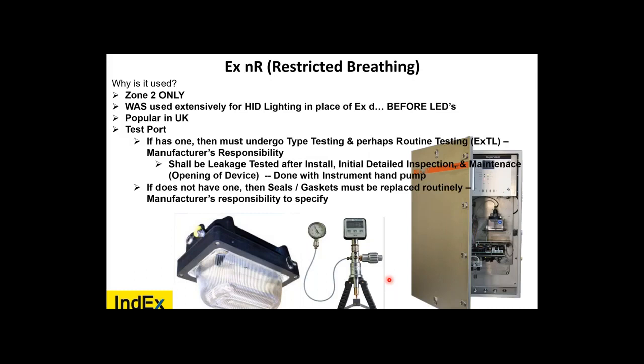Here's the problem with ATEX: manufacturer self-declaration. Now, if you involve an ATEX notified body like Ex NB or other ones, well, they know how to do the testing, or I should say, know which testing has to be done and who it can be sent to. Now, does it have to have a test port? Well, if it does have a test port, then it must undergo type testing and perhaps routine testing by an Ex TL test laboratory. And it's the manufacturer's responsibility.